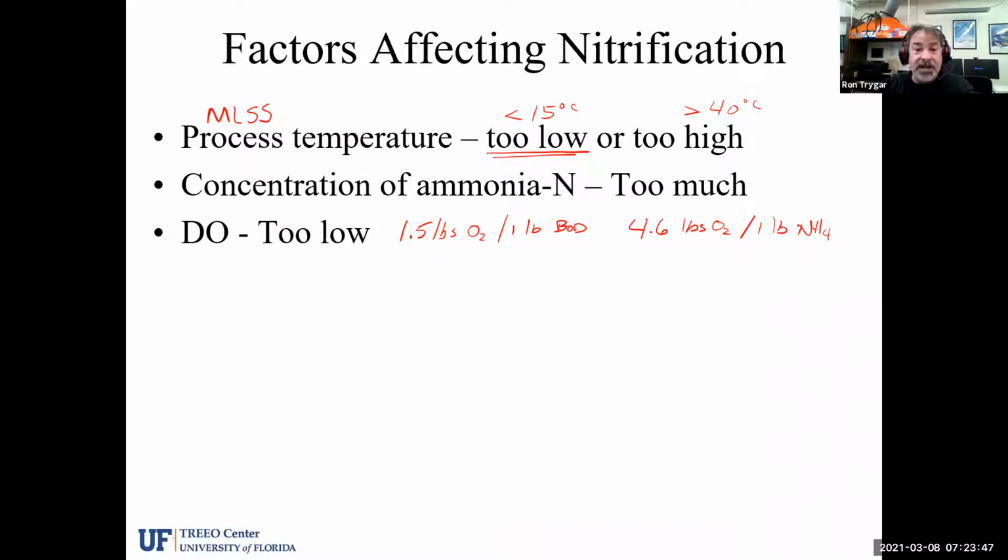That's why the aeration tanks are generally much bigger in BNR, or biological nitrogen removal plants, and the capacity to put the air in there is generally much higher as far as horsepower of the mechanical aerators or the horsepower of the blowers. And the efficiency of the diffusers is important in this case. We usually have to have good, efficient transfer of oxygen into the mixed liquor.